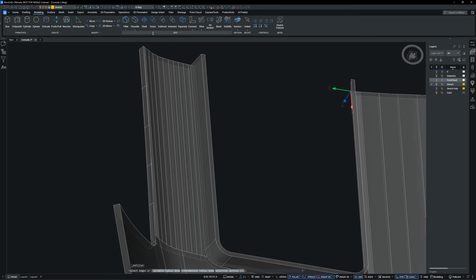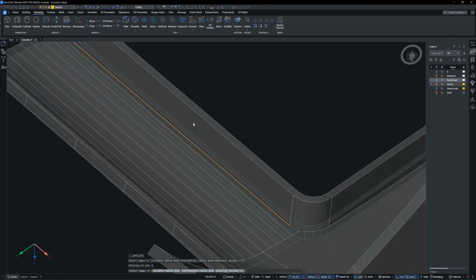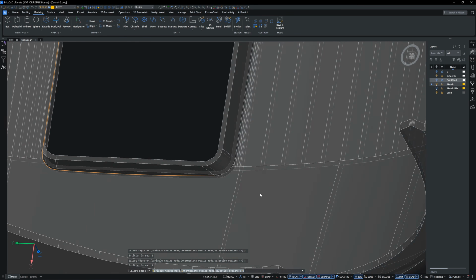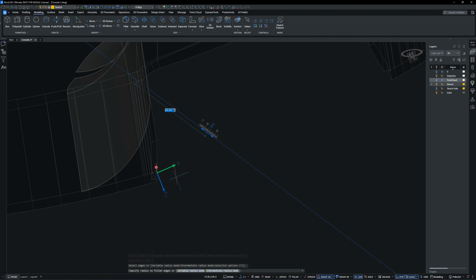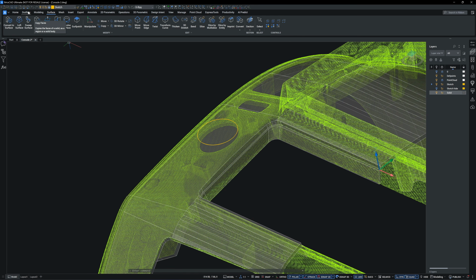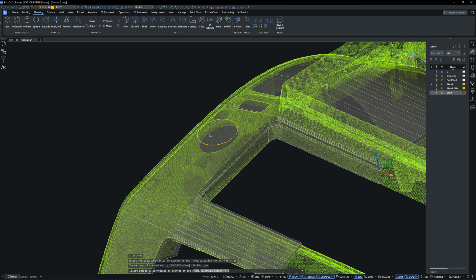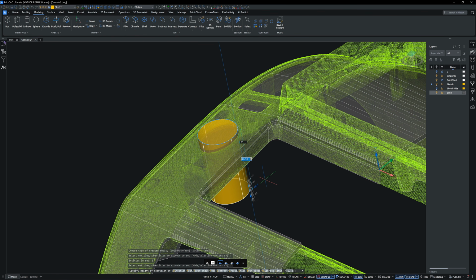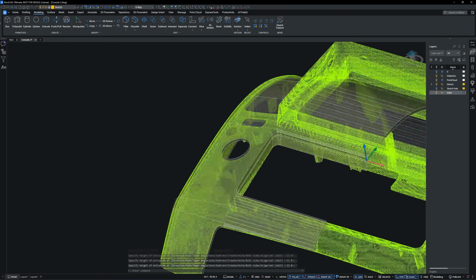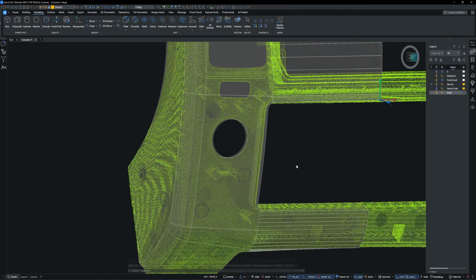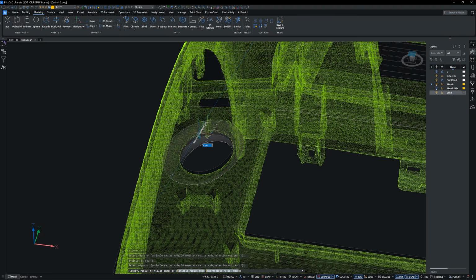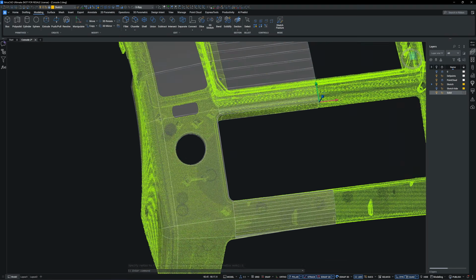Because the joint between the support wall and the bezel is very thin, I add a fillet to increase the thickness along this joint. Next, I create a cutout for the emergency light button. I use the 3-point UCS to snap onto the surrounding surface of the circle and build the cutting sketch profile. Then I round the cutting edge with a 1mm fillet.